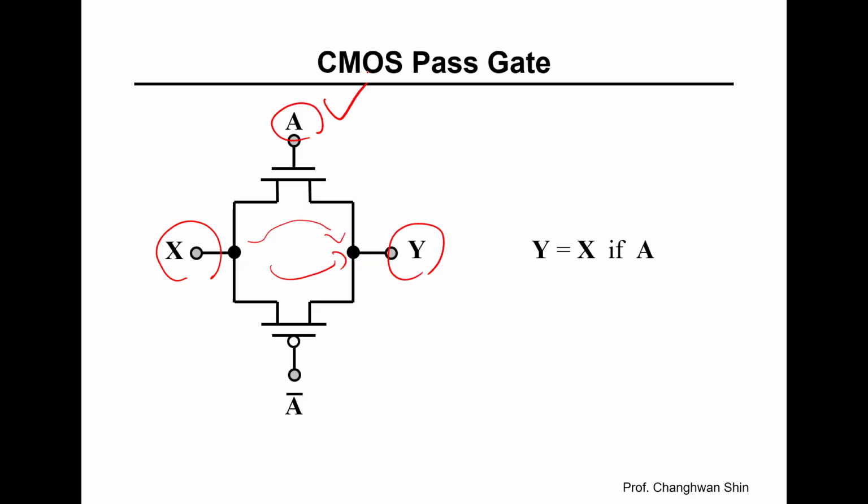So in digital circuits, pass gates are crucial for building multiplexers, memory cells, and other selective routing structures. They allow signals to be channeled dynamically based on control inputs. For example, in a data bus, pass gates might determine which device gets to place its data on the shared lines at any given moment, similar to how traffic lights control which lane of cars gets to enter an intersection.